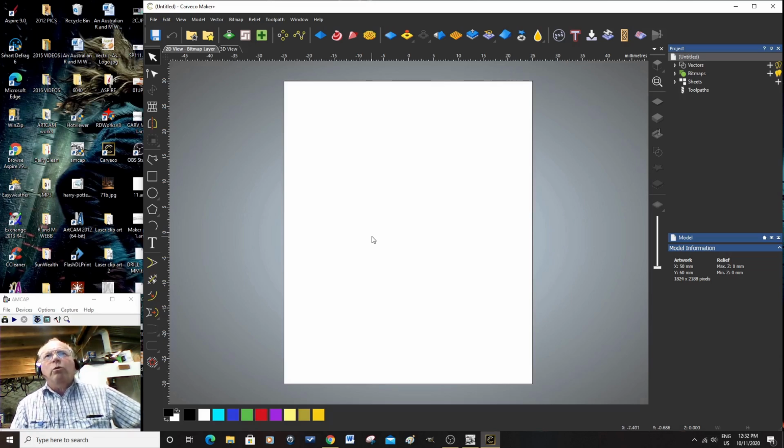So what I'm going to do, to make things a little easier visually, is fetch some guidelines out now and position them on the drawing here, just to make things appear a little easier for you to work with. I find them useful anyway. You just go over here onto the ruler, left click, hold down, and you can drag a line out and position it fairly accurately like that.